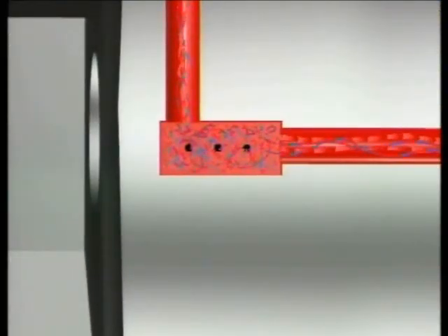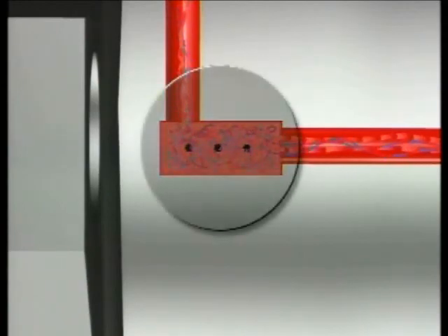This cavity or reservoir will be covered by a Welch plug. The holes shown here deliver the fuel when the engine is idling or under light load. Some carburetors provide a mixing area within the pilot jet itself. Different pilot jets are used in various carburetors, depending on the application.